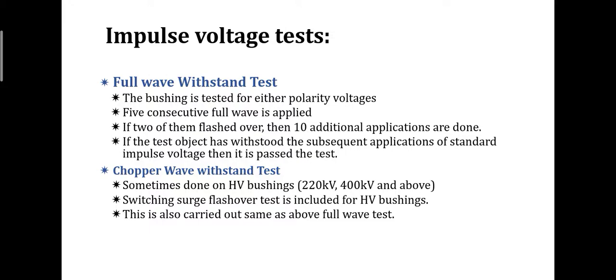The chopped wave withstand test is sometimes done on HV bushings, that is 220 kV, 400 kV and above. Switching surge flashover test is used for HV bushings. These are also carried out the same as the above full wave test. The test is conducted in chopped wave test only.